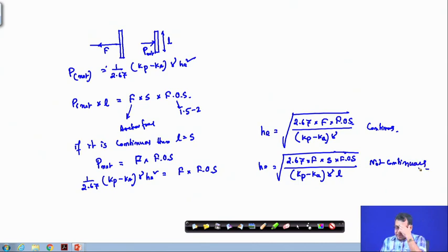So, remember that S is the spacing between the anchor rods, and L is the length of the anchor rods. If it is continuous, then S is equal to L. This way I can get the He, and I will show you in the next class with an example problem how I will get the He and how I will place the anchor from the sheet pile. Okay. Thank you.